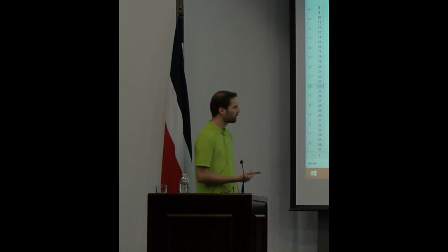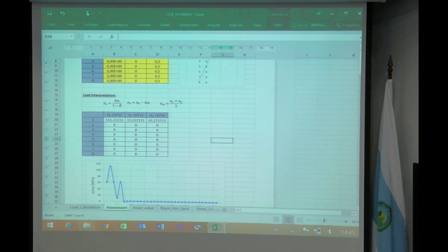And a stress ratio of 0.1 is usually the ratio at which fatigue tests are done, because there you have a low amount of cycles, so it's not as cost extensive, and also you're not going through the zero into the compression, which is always a little bit not as good for the testing machines, but also for the steering in itself. So what is happening if we change now our stress ratio?